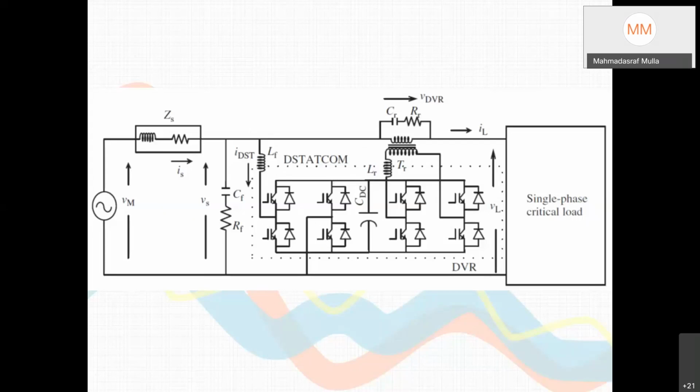Unified power flow controller. So irrespective of any situation, you can provide a fixed voltage now. Maybe hypothetically, make my voltage the same as the sending end voltage. It is possible here. We draw extra active power from here, and through this series injection we can increase the value of this voltage to higher than what is possible with series compensation or shunt compensation.